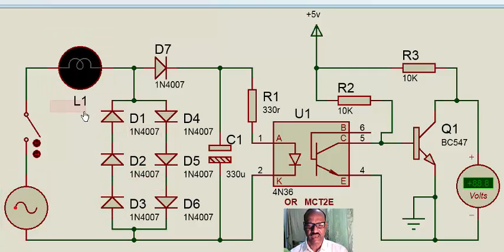In the process, what happens, while the load is switched on, we get about 0.6 into 3, about 1.8 volts, and which is then rectified and fed to a filter capacitor, where we get roughly about 2 plus volts. We have used deliberately 2 back-to-back in order to allow the AC current to flow.